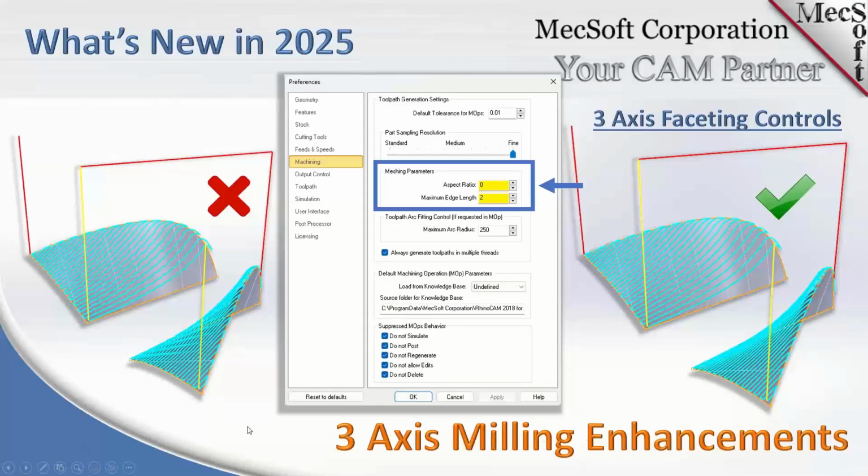Actually, sorry, Don, the problem occurs only in one class of surfaces, which is ruled surfaces. When you have a ruled surface where one side is quite a bit different from the other side, particularly in this case that Don is showing, a twisted ruled surface where the rulings are quite a bit different from one side to the other, that's when you see these issues, and that's where these mesh parameters will be applied. And again, we're going to show you that in the actual part coming up in a demo.